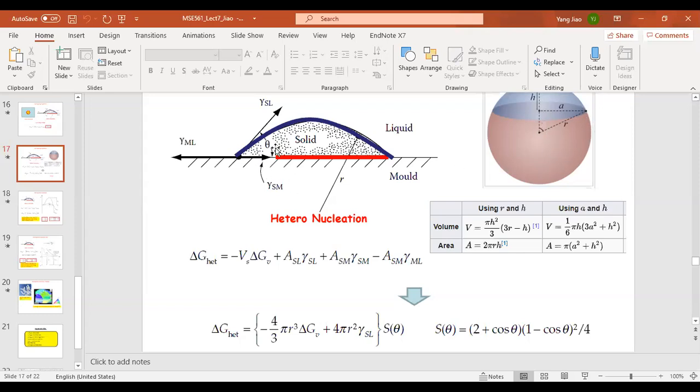And theta can be computed in terms of the interfacial energies, these gamma things, right? Because at this point, we have the balance between all the surface tension forces, and the surface tension is essentially this particular interfacial energy form. So you have a very simple relation which we derived, and you have theta. Once you know the geometry, you can easily use these equations, which I just copied and pasted from Wikipedia, and multiple sources you can get them, right?